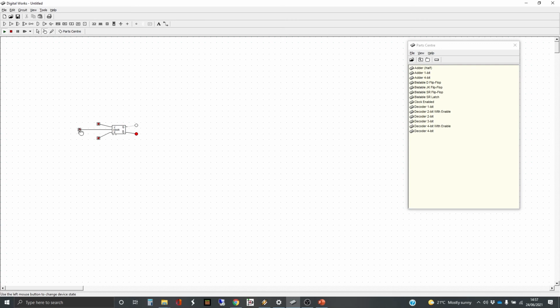flipping and flopping. In this state, this is sometimes called a T flip-flop or a toggle flip-flop. And sometimes all you want is for this toggle to happen. So you connect both the J and the K together and to a constant 1. And then you put a pulse in here. And in fact, let's do a little demonstration to show that. Let's change these inputs, and we can leave the outputs the same, which is fine.